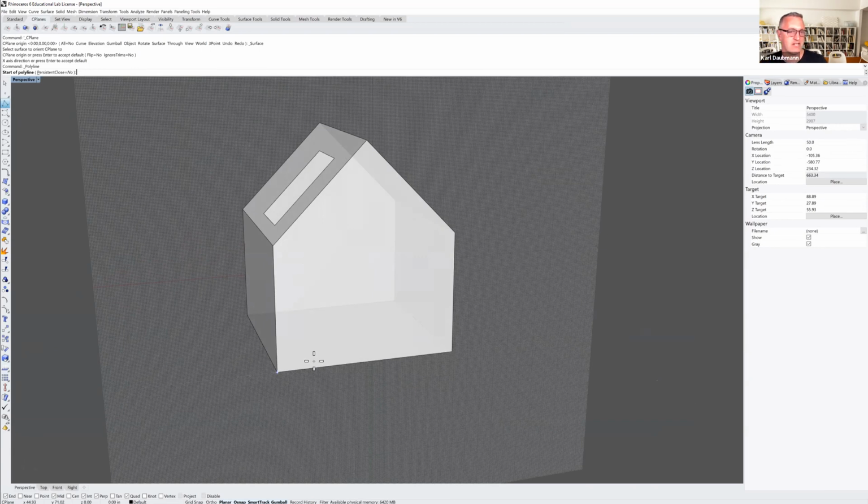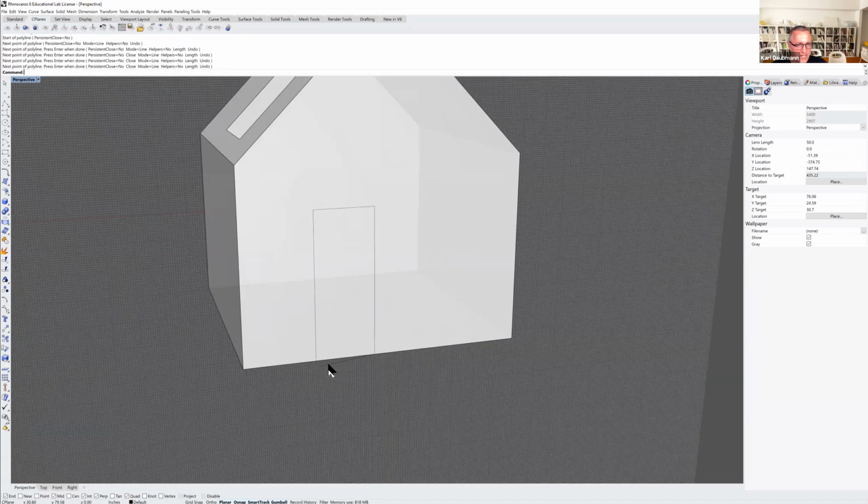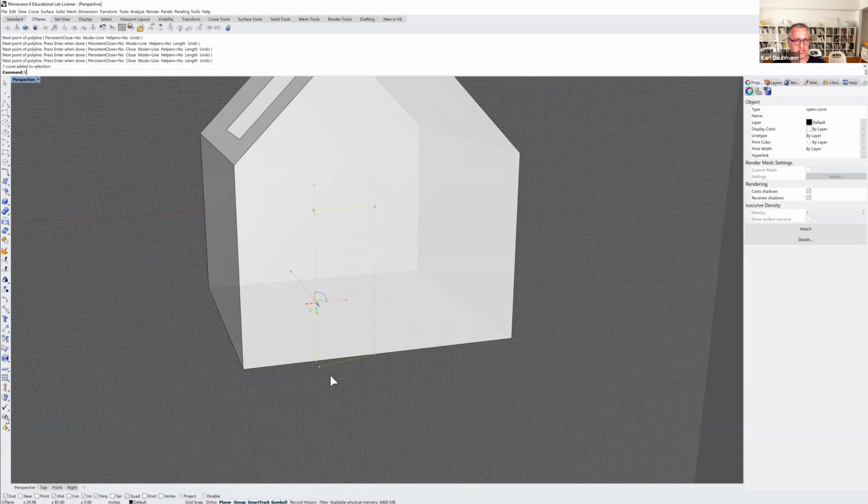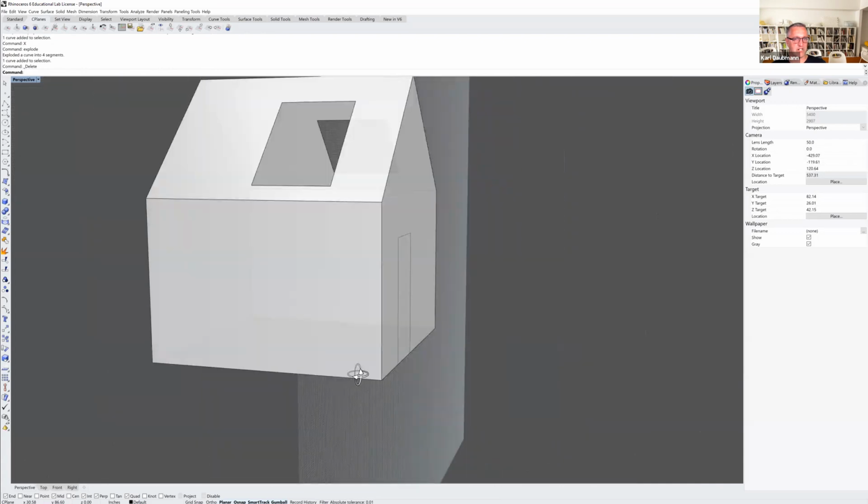And so if I wanted to draw something here, and here's another little trick, the snaps are pretty smart. So if I want to draw, say, a door, as I snap to the end point, it will also give me a kind of orthogonal or perpendicular on there. And I can draw up and over and then down until it hits that snap. Oh, and then I was sloppy with that. So I can explode it. Delete that last line, right? If I wanted to trim that out.